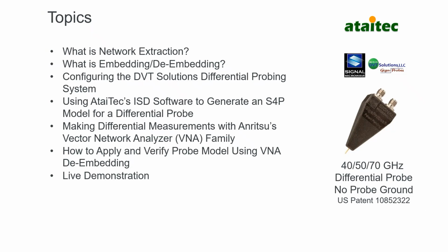And Brian will also take us through the ISD software and how we generate, using that software, the S4P model for a differential probe. Then I will discuss Anritsu's VNA family and how we make differential measurements, which is critical here because we're trying to obviously get differential measurement results. So we need a 4-port VNA to do that.